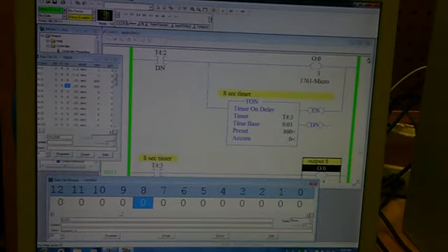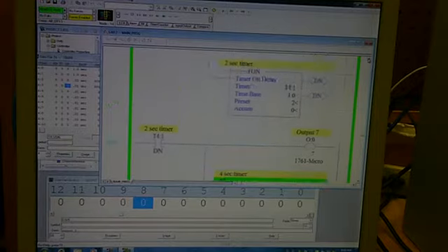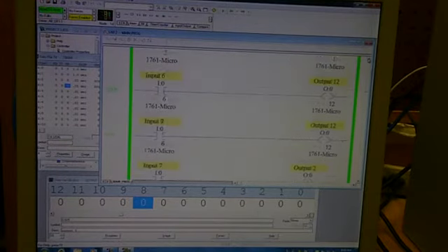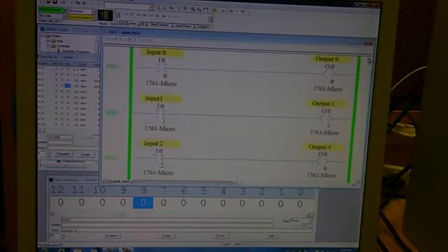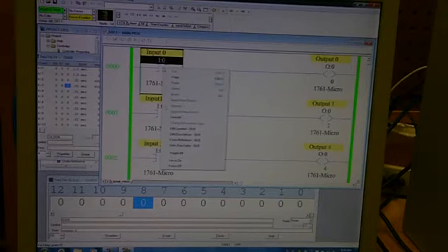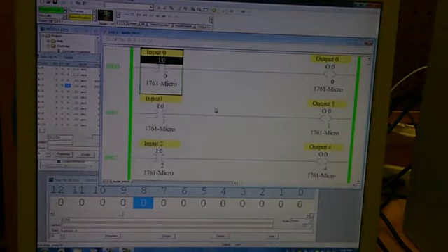Okay, now, in the emulator, what we would do is go and do a toggle. So I'd go here and I'd toggle the bit. Now, if I toggle the bit when I'm using the real hardware, it's not going to do anything. What it did is it toggled the bit for one program scan. One program scan is probably 10,000th of a second with this program. So that means we had no chance of seeing anything come on.